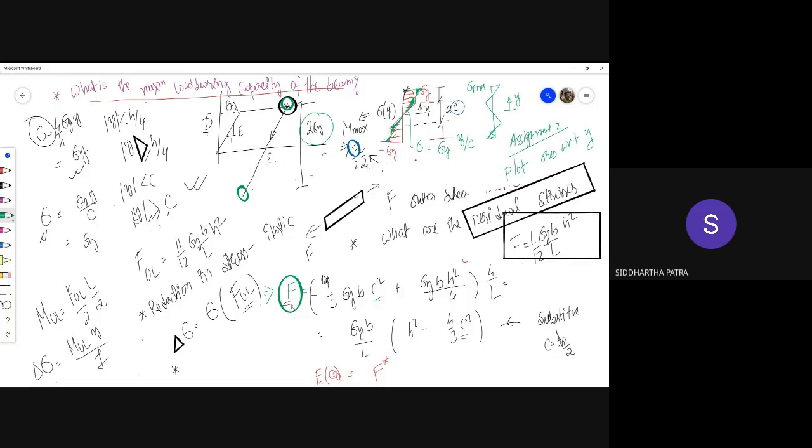So you unload the force that you used to have the elastic core of certain size, but while you are loading you had an elastoplastic stress distribution. When you unload, it is only an elastic stress distribution that needs to be subtracted. Okay, so the green curve is not a stress distribution, it is the change in the stress distribution.